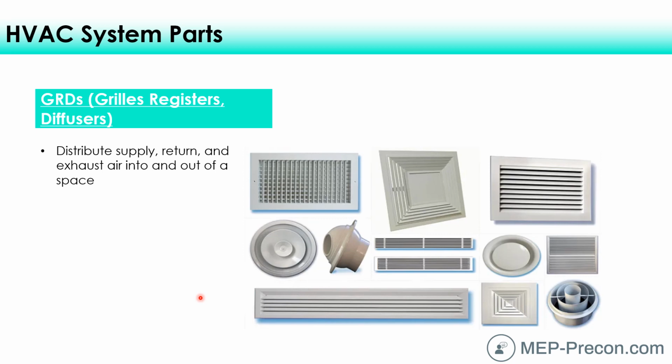So a diffuser is just the opposite. It takes that stream of air and it opens it up. So as you can imagine, it opens it up here. It does the opposite of a nozzle, and so it slows down the air. So we want to spread the air out and slow it down so that it doesn't create any harsh drafts on the backs of their necks. That would be kind of uncomfortable. So that's how a diffuser works.